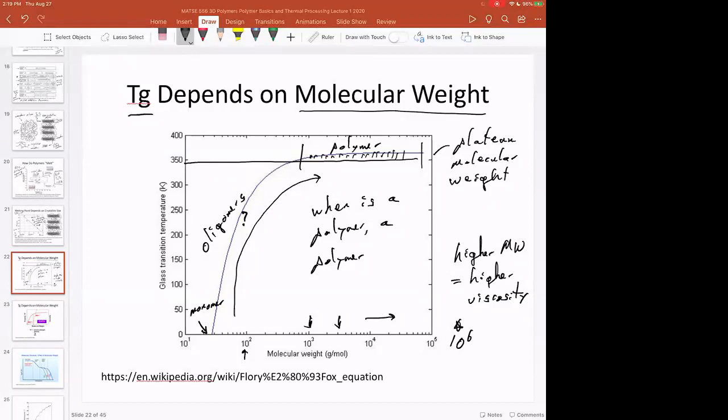So not every polymer has quantitative TG versus molecular weight characterization. But there is a lot of viscosity versus molecular weight. There's a direct way to measure molecular weight, which is called size exclusion chromatography. And so there are ways to directly measure molecular weight, just not DSC. Okay, thank you. Great.